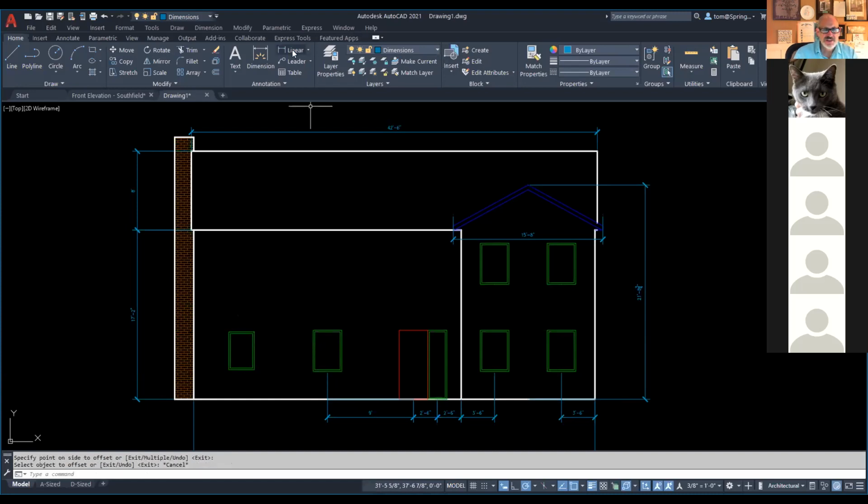Okay, and we'll put a dimension here, make sure this is correct. And that's also 9 feet. So we're good to go there. Then I want to copy those up 11 feet 8. So I'm going to copy these two up a distance of 11 feet 8. I'll touch it here just to get that as my orientation point, and we'll drop it there.